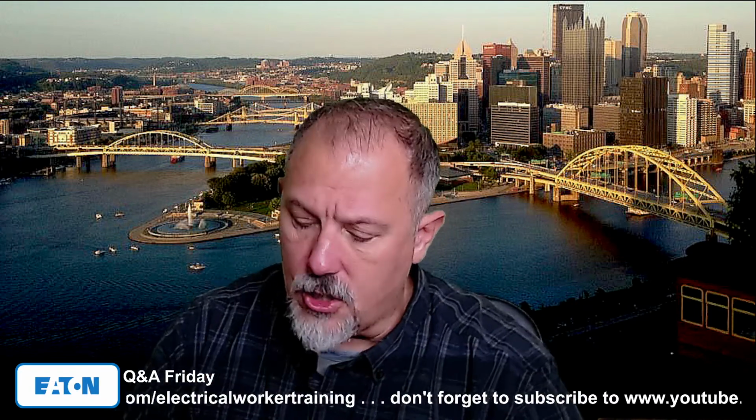But in many cases, we might need to put more than one conductor on a termination. And my message there is, follow the manufacturer's instructions. Many terminations will tell you not only how many conductors you can put, but the size differences, and quite possibly stranded versus solid. You might not be able to mix those. So just be careful. The moment you are going to put more than one conductor under a lug, that's a flag. Read the manufacturer's instructions. Do your homework before you take that action.